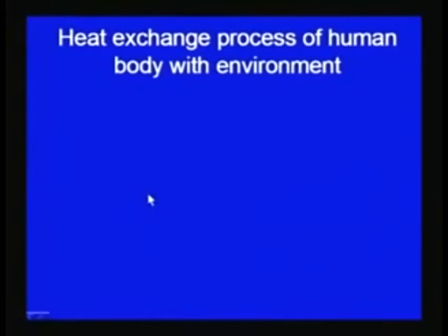And so, here we can see the air temperature and wall temperature significantly affect the way by which heat loss to the environment takes place by the different modes of heat transfer. For too high air and wall temperature, the heat loss mainly takes place by evaporation, while for low temperature conditions, it is the combination of all three, where convection dominates and evaporation is the minimum one.